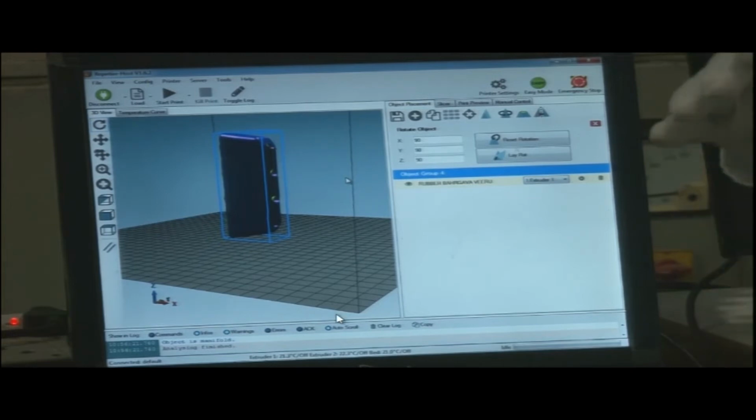What is the drawback when we increase height? Because it is manufacturing layer by layer, this is very important to note. If we increase the height, the total time would increase. So the height has to be optimized, it has to be minimum. So many layers are to be deposited, so the total time would increase.